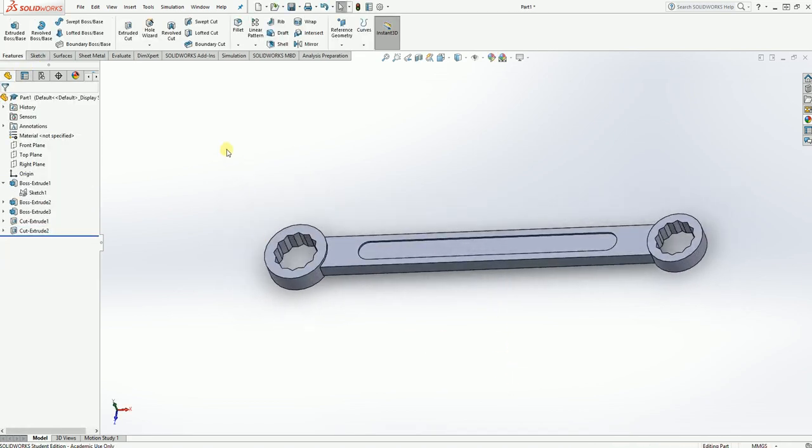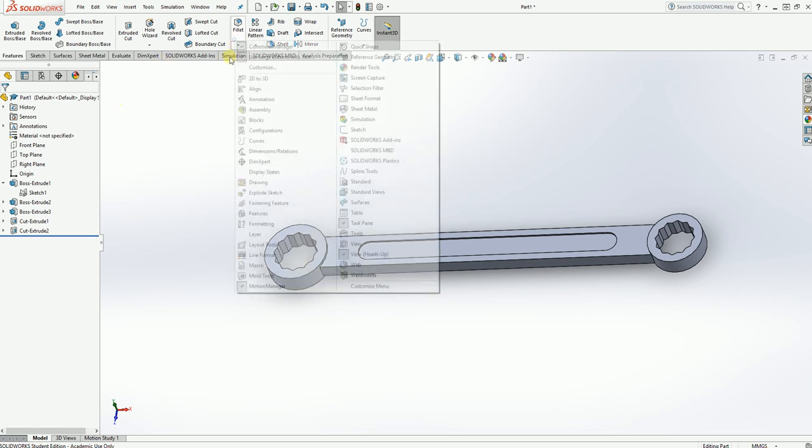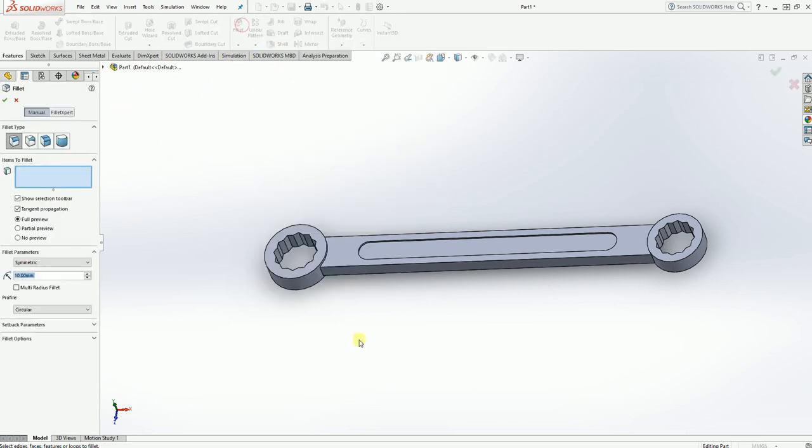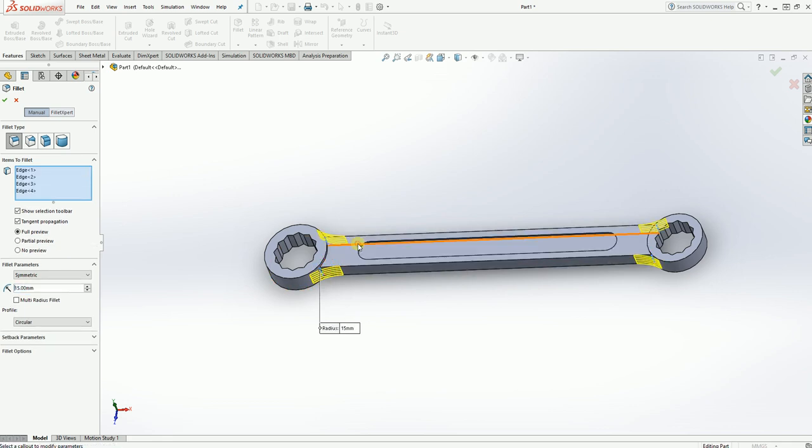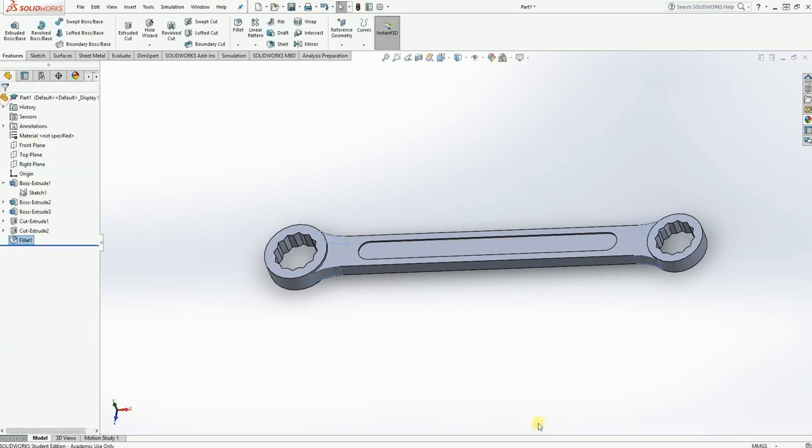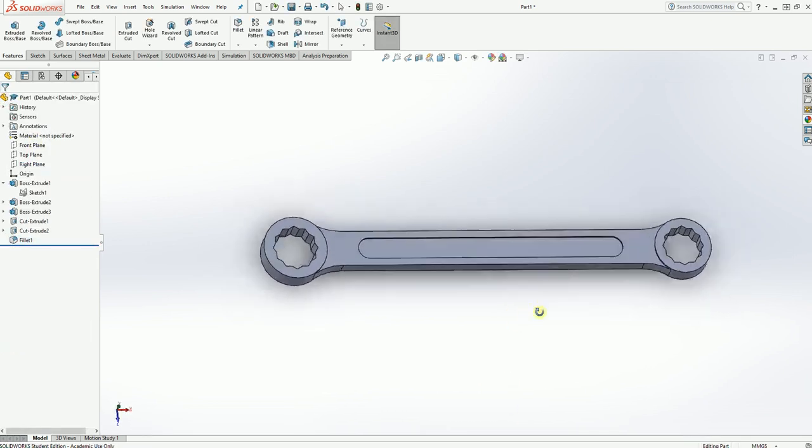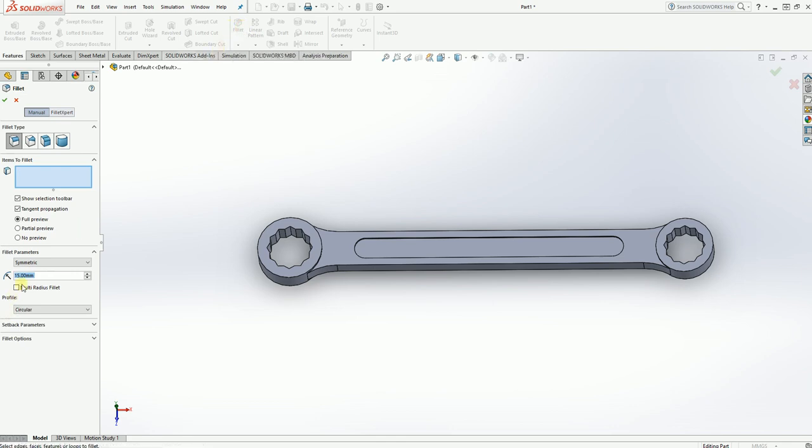There we go. I'm going to add some fillets in now as it shows on there. So fillet, these big ones are 15s, so that's that edge. I'll use the little quick menu. Yeah, that picks the 4 corners I want. Yeah, starting to look very much like a spanner now. Then it just says to put a little 0.5 on the edges, just to round it off nicely.